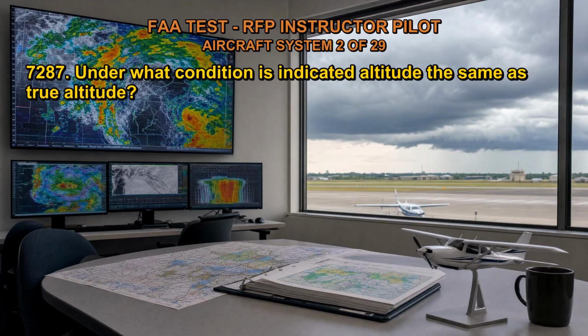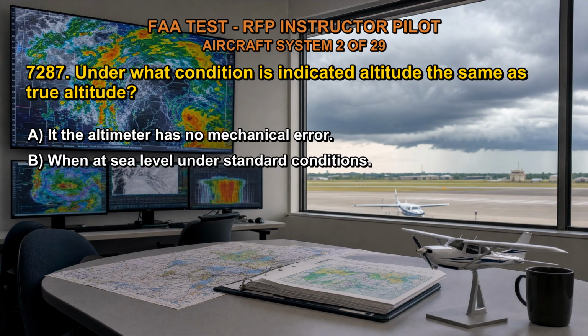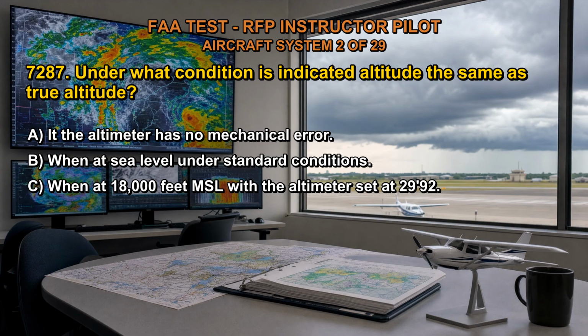7287. Under what condition is indicated altitude the same as true altitude? A. If the altimeter has no mechanical error. B. When at sea level under standard conditions. C. When at 18,000 feet MSL with the altimeter set at 29.92 inches.